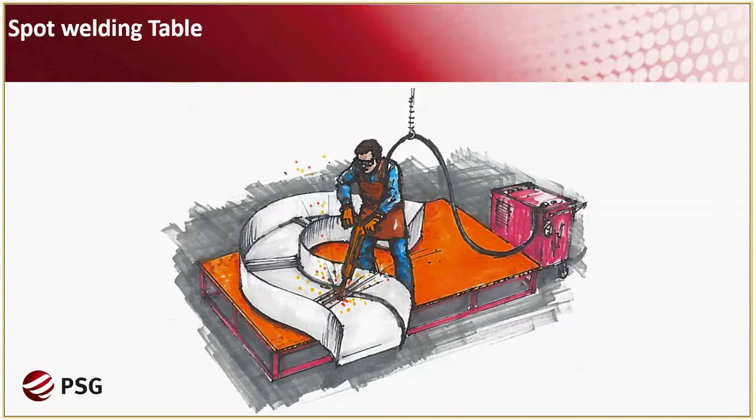Spot welding tables were of essence, and most shops that considered themselves serious sign shops had one. It was the only way that you could manipulate and make large channel letters and spot weld these components into the back and make sturdy letters. This really involved an electrode that would be in contact with the copper table that would conduct the necessary current to establish that weld point. Hence the word spot welding.